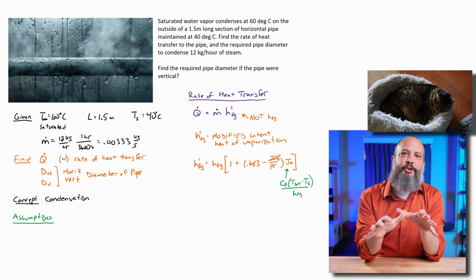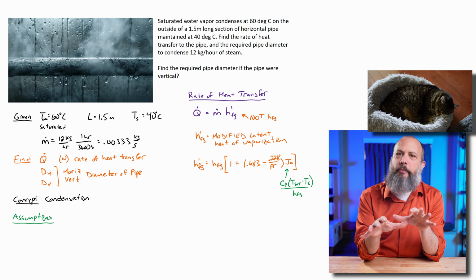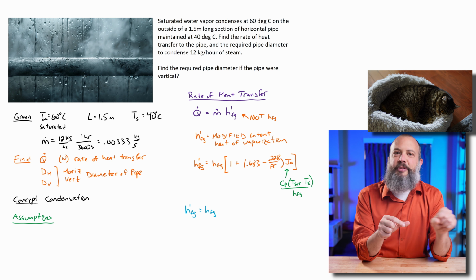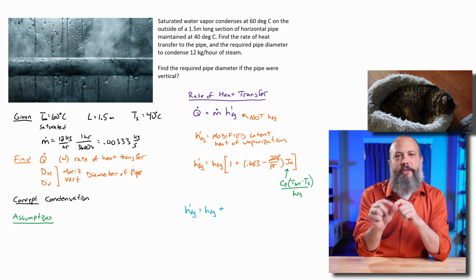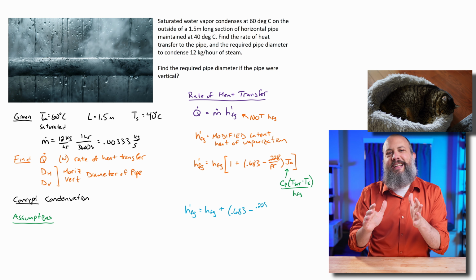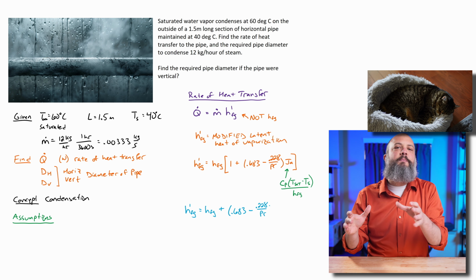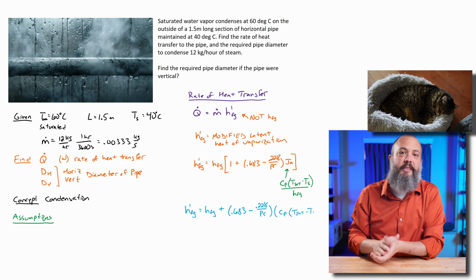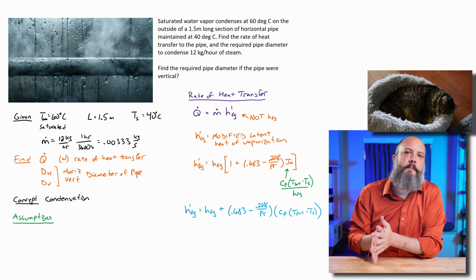And so if I rearrange this equation, it'll now probably look pretty similar to the equation in other textbooks with the 0.683 term, just with this extra little adjustment based on the Prandtl number, as in the amount of heat that is used is a little bit different based on temperature. And the Prandtl number changes based on temperature.